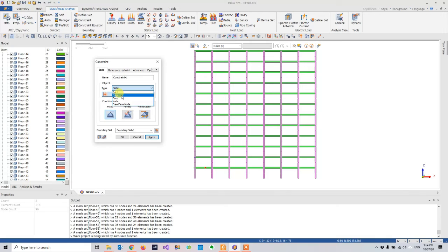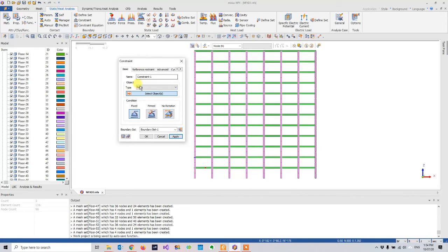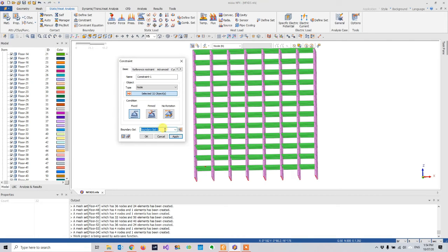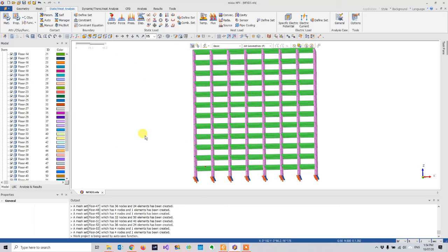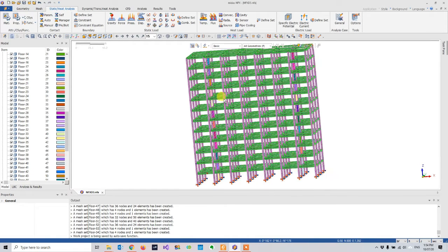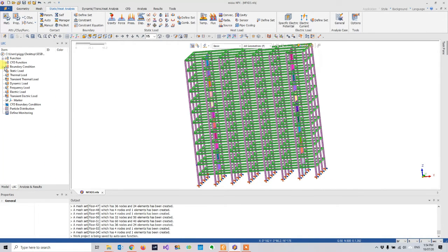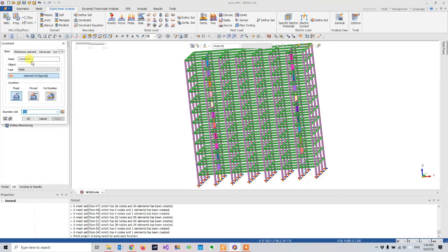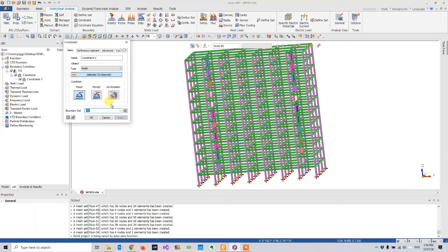So we are actually now dealing with the mesh element, the nodes. So with the nodes selected, you should be able to see the highlighted nodes, and we will select the whole nodes here, and let's put it as a fixed boundary condition set. So all the information will be kept in the second tab, boundary condition fixed. So you can access the value by right click and edit, and you can change the value at any time.